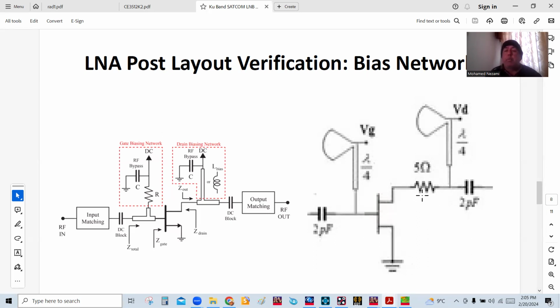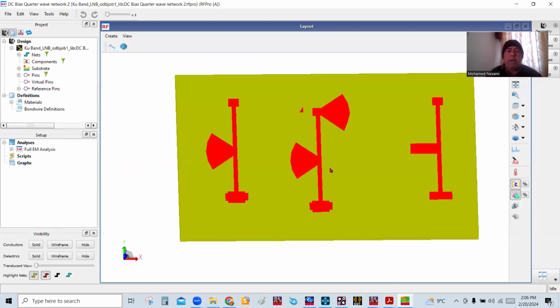And some people put a capacitor in here so that they can actually control where this shows up. Some people say, it's stable over this part of the band, but this part of the band is not stable. So what they sometimes do is bypass this with a capacitor so that it is only present in another frequency region, because this reduces the gain a little bit, okay? All right, so let's go back to here.